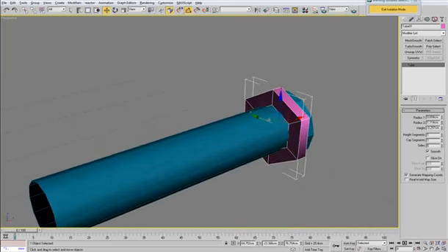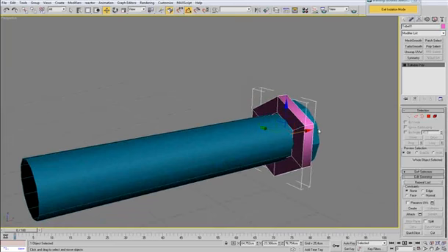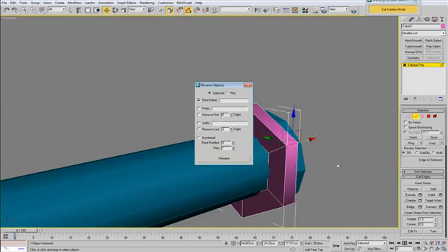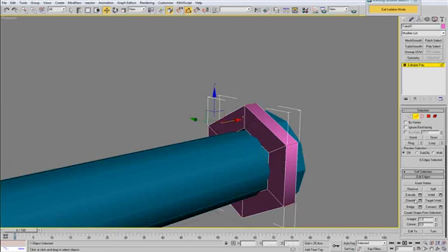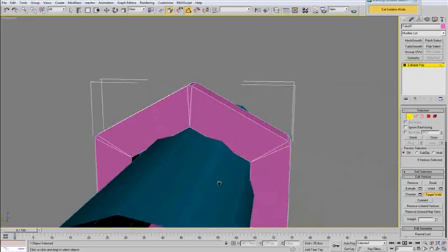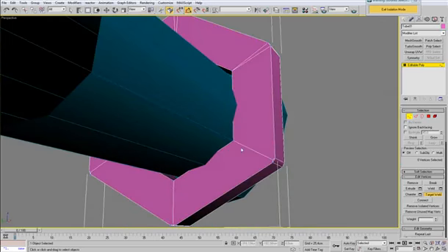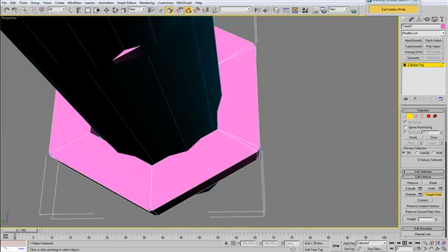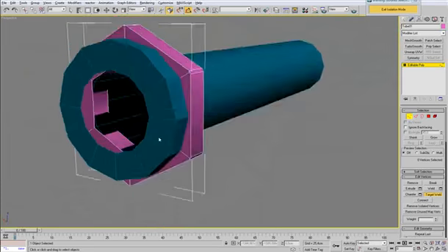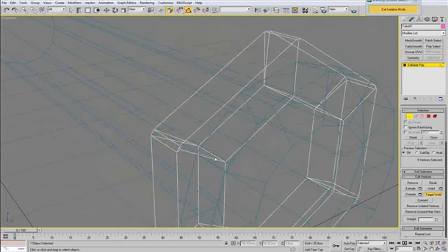Now when we adjust the measurements, we go ahead to editable poly, and first we have to chamfer those 6 edges there, because we need to harden the edges, and otherwise if we apply mesh smooth, everything will go round, but we need them to stay hard here.